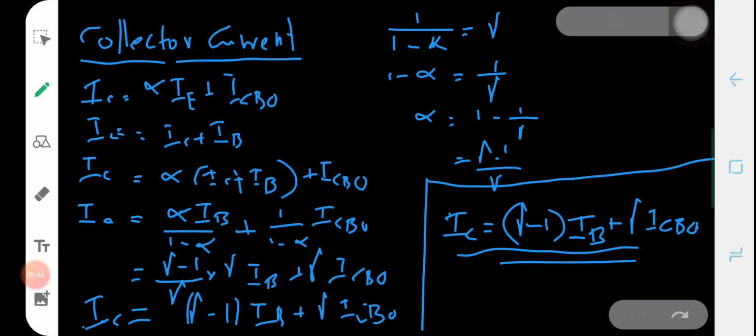Even though there is a high current gain, since the input resistance is much higher than the output resistance, there is no voltage amplification, and the voltage gain in the case of a common collector connection is less than 1. So this type of connection is seldom used for amplification purposes. This is used for impedance matching circuits.